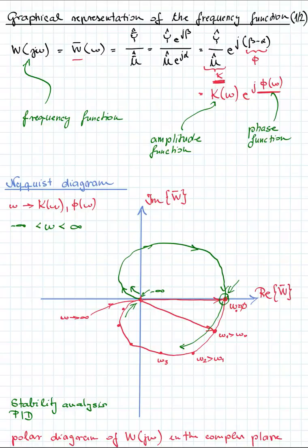But it is enough to obtain the Nyquist diagram for the positive omegas, and then the diagram can be mirrored to the real axis because of this property of the Nyquist diagram. So we are going to come back to here at the stability analysis and for the PID controller design. In the next video, I am going to show you the Bode diagram.